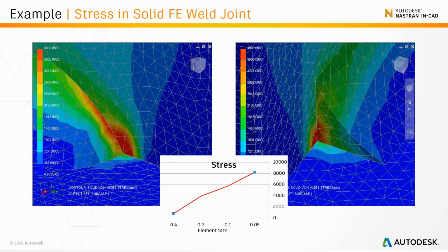So we've analyzed the structure, and you can see here that what ends up happening is we get diverging stress at a singularity on both sides of the structure. And looking at the welds up close, you can actually see that though the geometry is different, we're still getting the same outcome, and the outcome is not reliable. It's hard for us to trust the results of those. So this is really proving to us that you're forcing, in essence, though, what we could do is look at modifying the geometry to try and get the geometry to give us a more accurate result, but then how accurate is that geometry in respect to the physical part that we're trying to represent?